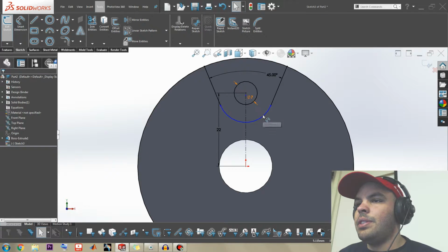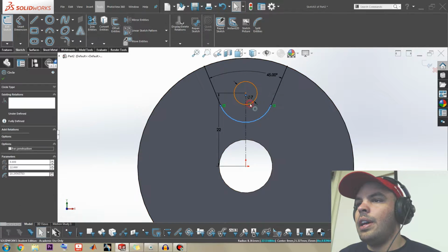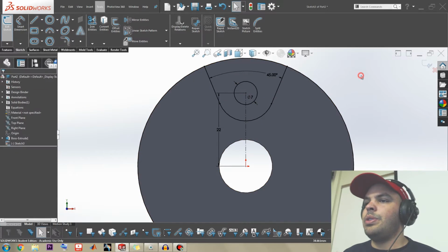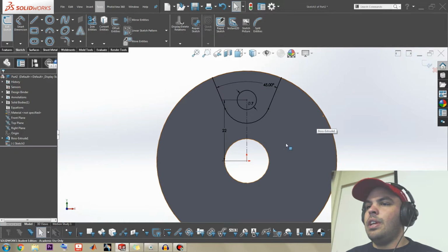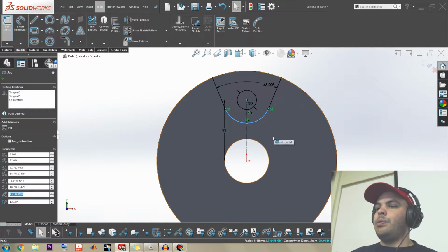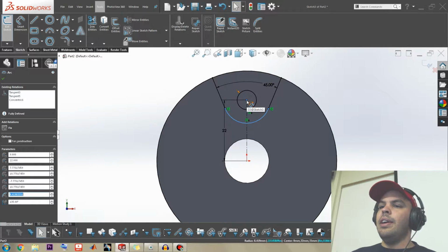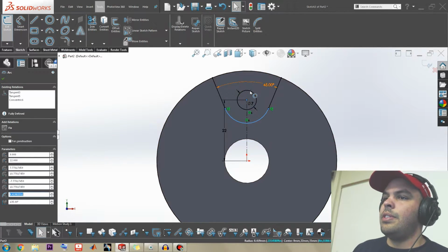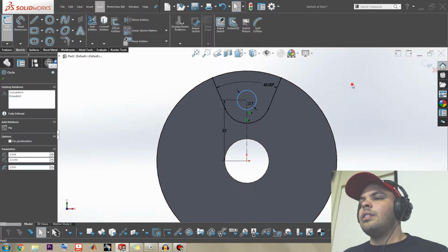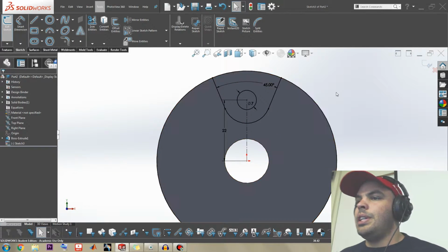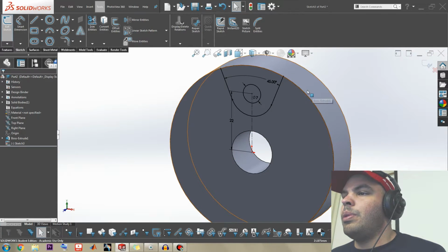And the last bit is that, and that will make them concentric. And that fully defines it. This arc is fully defined because these two lines go through this point. If you extend it out far enough, they both go through this point, and they are tangent, and it is locked in place by sharing the same center as this circle right here. So that's pretty neat.